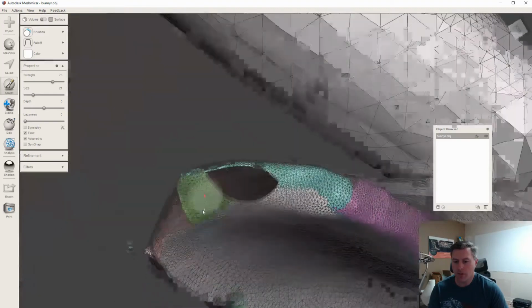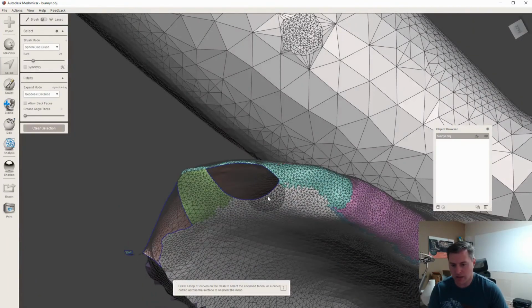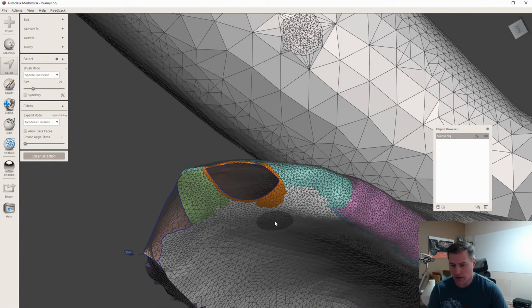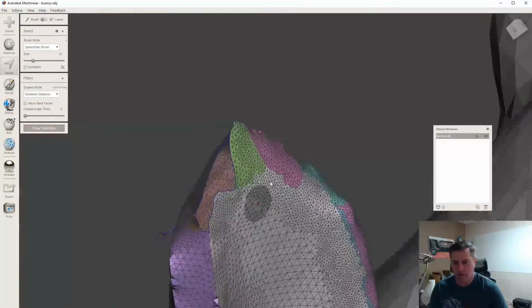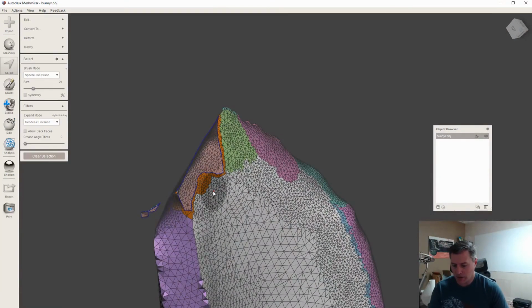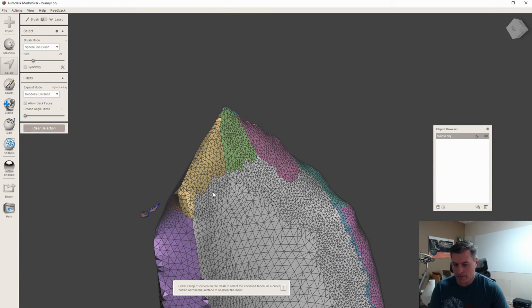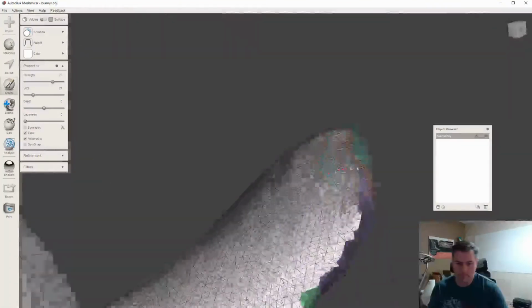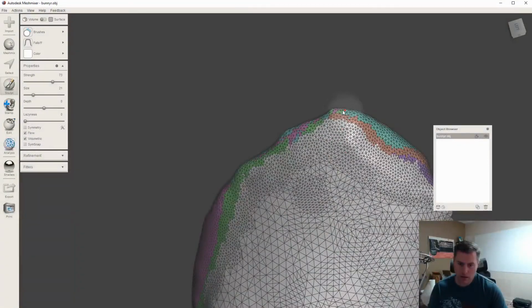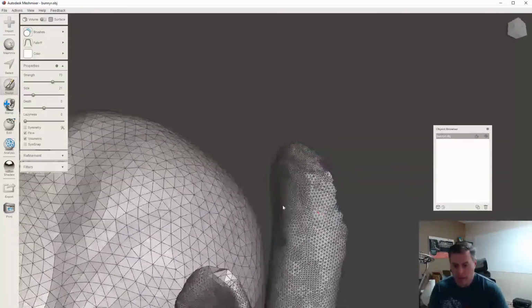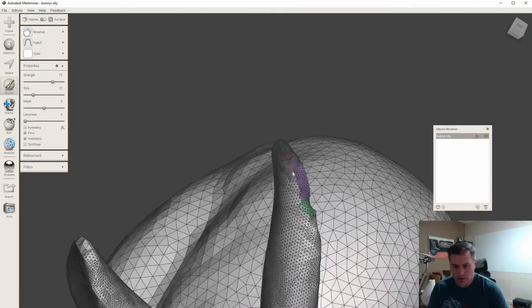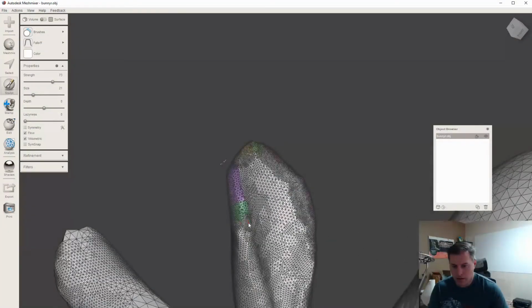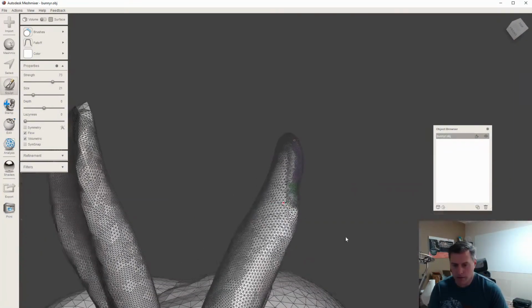zippering this up. But once this is a nice hole like this, you can just select, double click on that, and hit F for fill. And that's probably a little bit faster. And this is now a nice one that we can fill as well. And I'll go back and just do some robust smoothing on that to get the jaggies down. And a little bit. And we have actually a nice ear. A little bit rough on this side. Go back. And that is a pretty good thing.